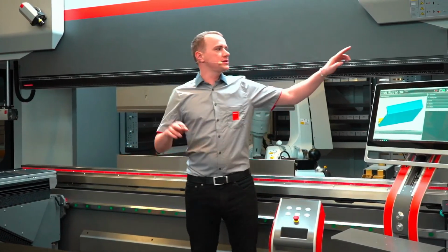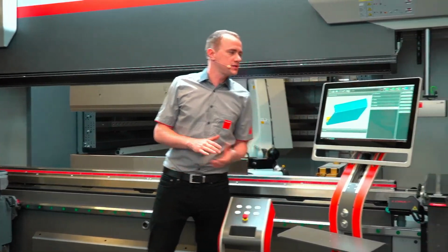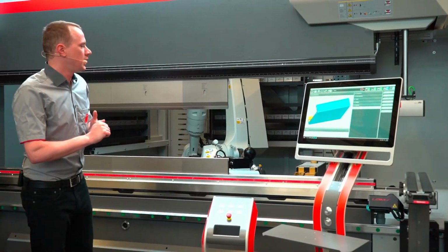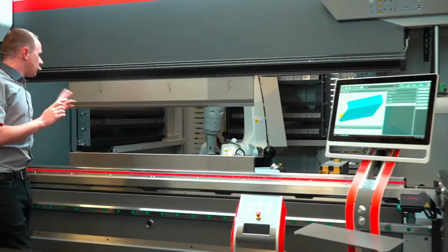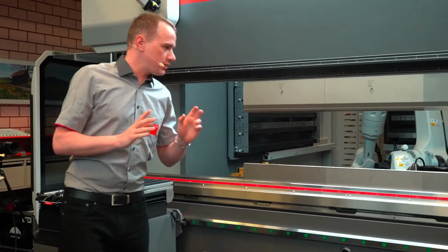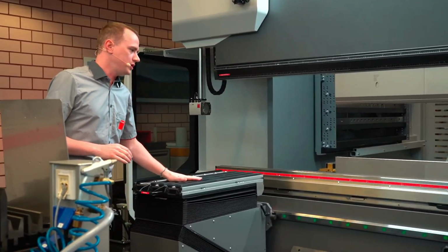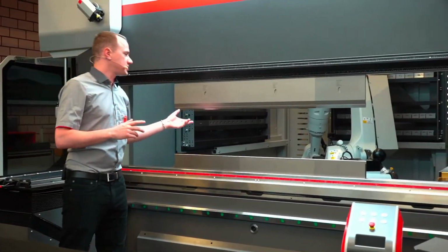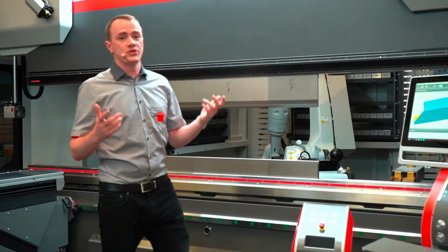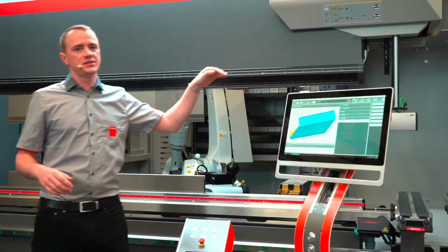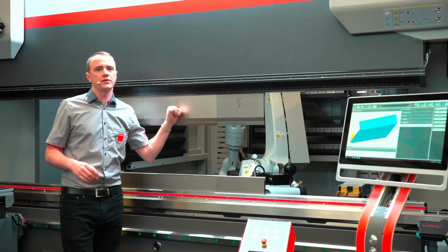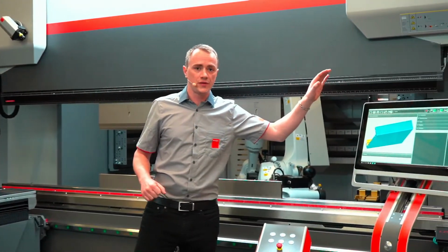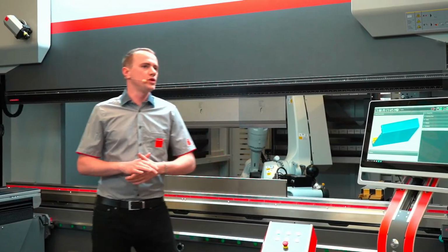Also standard are sliding doors on the side and the fastbend system. The fastbend system is the protection for the operator, so he's not breaking his fingers or whatever. And a 4-axis backgauge is standard. What is an extra option here is a bending aid. We also have a laser angle measurement system here, a 6-axis backgauge, and the extension, but these are all options. And we have a fastbend plus system, which automatically adapts to the programmed height of the upper tools. So if you change the height of the tools a lot, it's very helpful to have fastbend plus, the automatic system which moves up and down.